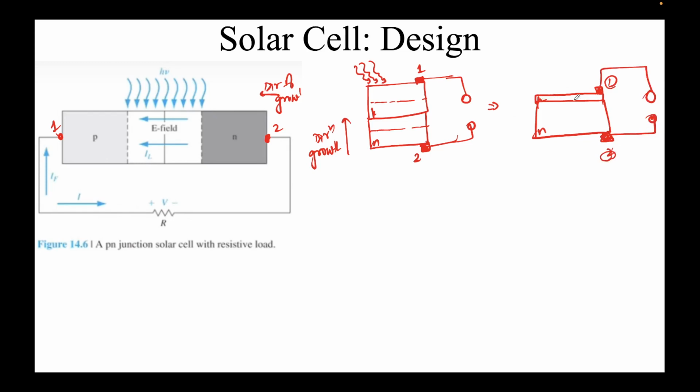All right, what usually happens is that you also need to make this contact. If you have thinned the p region, its resistance increases, and thus even if you are producing electrons, they will not be transported out efficiently. That's why we need to dope this high, p plus type. Then it works. Even if it's thin, the resistance is low enough that this contact is a non-rectifying contact and works properly. So this is p plus, and this is n, so the depletion region will extend into the n side, with very little in the p region. So this is how your design will essentially look: a p plus and an n, with your depletion region extending naturally into the n side.